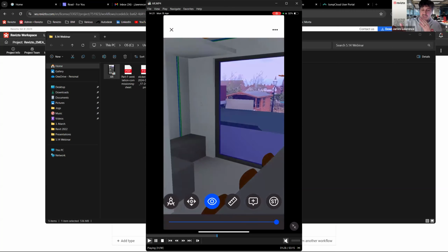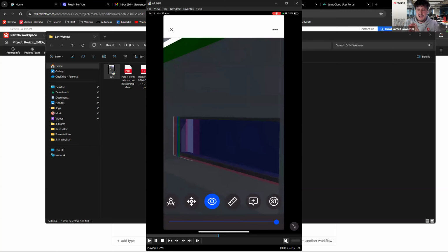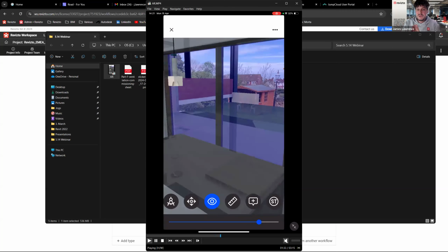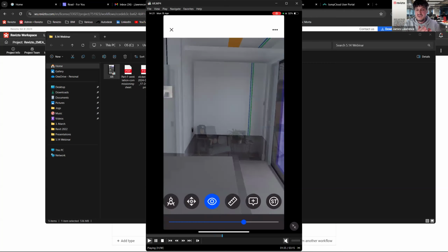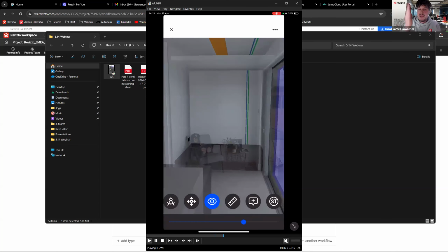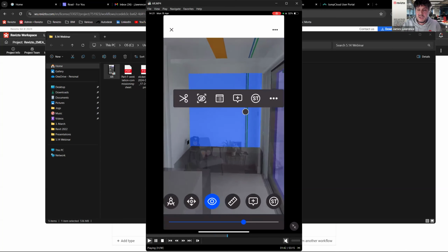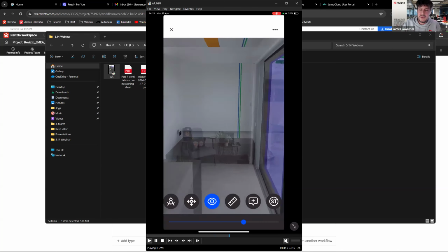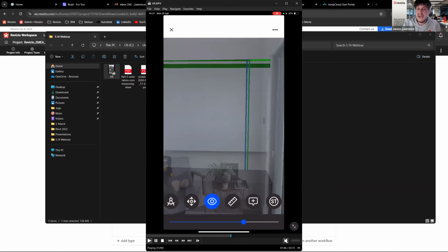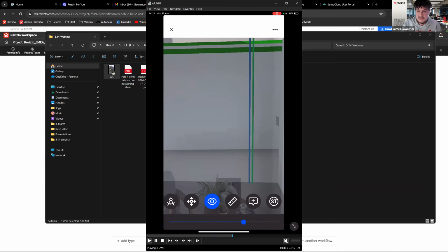And by having the transparency fully on now, I can check the model, walk around, the double doors are in place, start changing the transparency as I go through. And then by going to the back of the kitchen, I can now see that we have pipe work going into a completely random area. So I'm going to hide some items to see if we actually have a manifold for the underfloor heating.